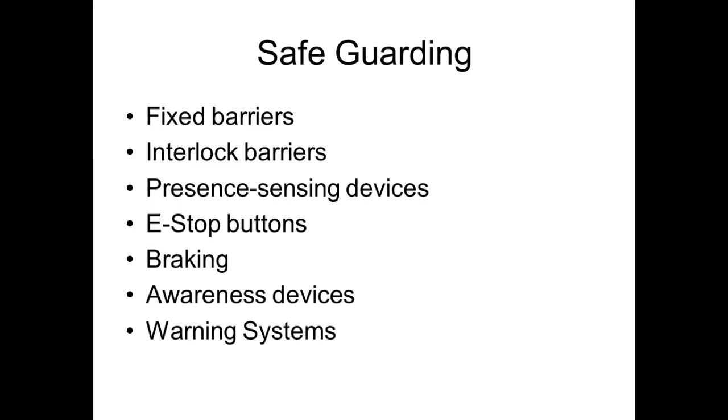We program these robots that all have safeguard stuff, right? But remember, when you're in there programming, you're trying to pick up a block. You're trying to move it halfway down the block, make sure it's working. How are you going to tell when you get down halfway on the block? Odds are you're going to have to be in there with it, right? Or if you want to put it 5 millimeters above the surface, then by George, you're going to have to get in there and measure that. Because you can't let the robot in.